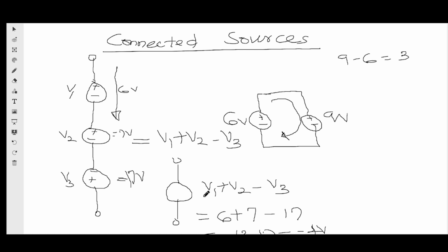What does that mean? It means that our minus will be up and our plus will be down, and we'll have 4 volts. Or if you don't want to draw it like this, we can say our plus will be up and our minus will be down, but it will be minus 4 volts. But it is more professional to draw it like this, which means that we are just switching the terminal. Do you understand? Okay, so that is that about that.